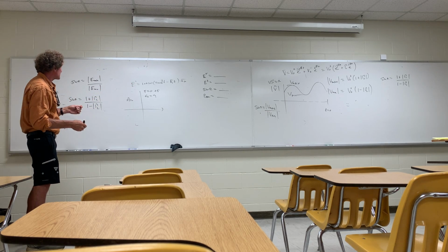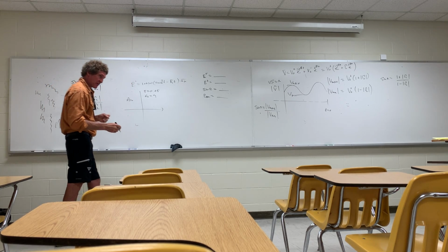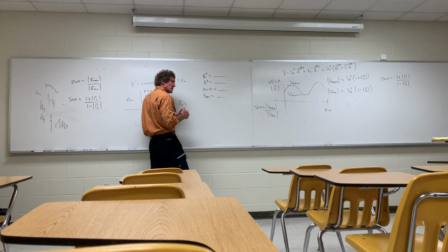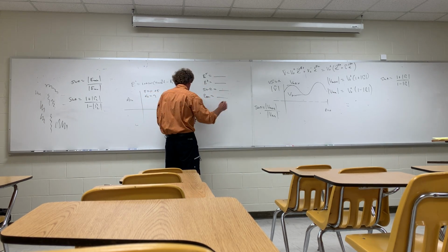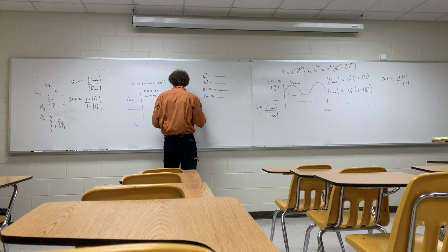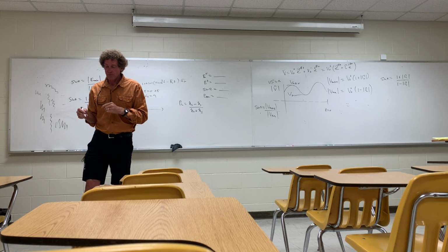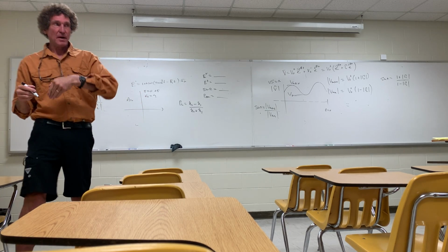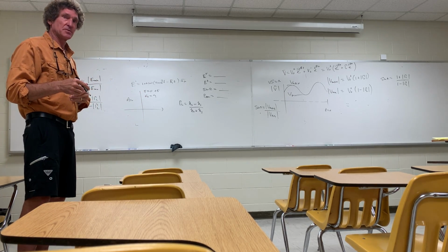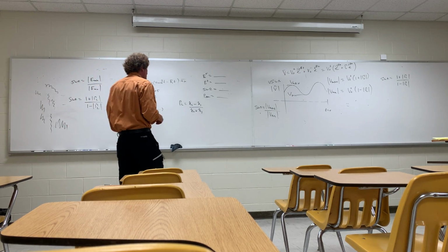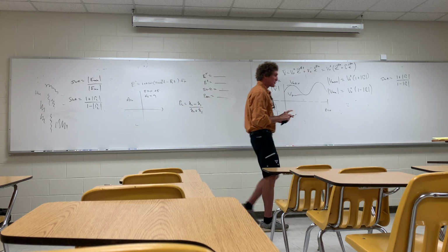But the reflection coefficient now changes a bit. Now the reflection coefficient is the impedance I'm going into, eta 2, minus the impedance I came from, eta 1, over eta 2 plus eta 1. Don't remember doing that? When we had reflection, you always go the impedance you're going into, minus the impedance you came from, over the sum of the two. That's the intrinsic impedance of the medium. So we're going to do it for this one. This is a good problem.